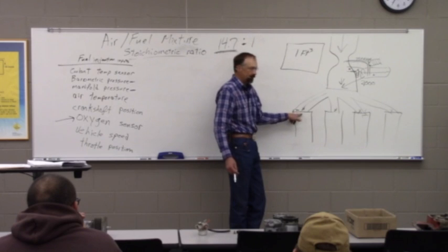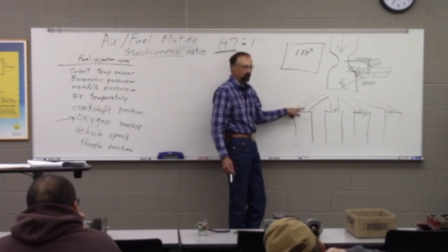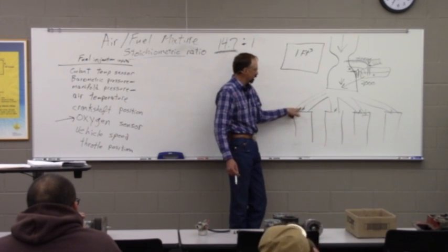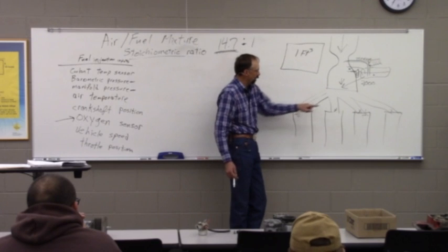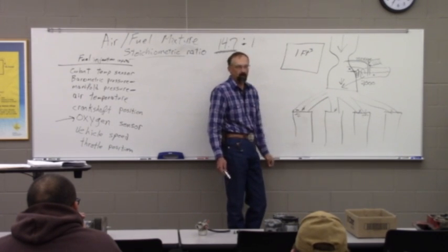So when this cylinder is getting air and needs fuel, we open that injector right here at this cylinder. And when it's not, we're going to shut that one and we're going to open one somewhere else that needs it right now. Does that make sense?